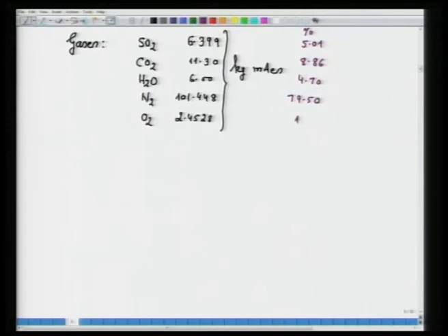The quality of heat will be very high, because the temperature of the flue gases is very high, at least the temperature of the smelter, 1000 or 1100 degrees Celsius. So, the higher the temperature, the higher the quality of heat. When the quality of heat is very high, it takes a very large amount of heat with it, and appropriate waste heat recovery devices must be thought of to recover the heat. So, that is what is important. Oxygen is 1.93%.